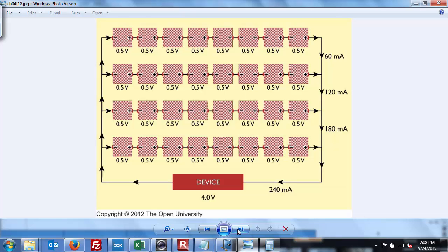I'm sure you've also started talking about series and parallel in DC, so all of these guys right here are in series. And I think you can also see why if one part of the panel is shaded, it more or less becomes a resistor, it becomes a liability, and all these photons end up kind of flowing into it and really messing up the circuit. So that's another good analogy for this. I guess another good analogy is locking the bullpen. If one of the padlocks is out of place, the whole thing's screwed up. So this is the importance of having a knowledge of series and parallel.